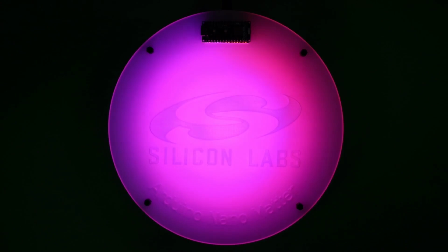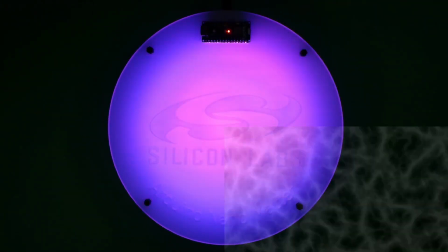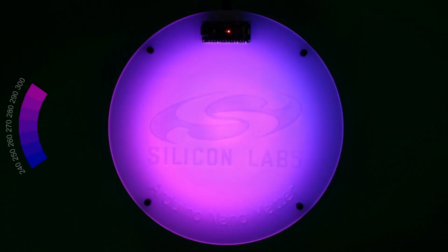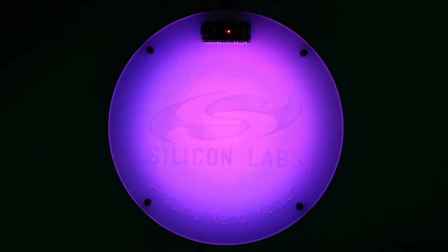The final stage adds 4 mood light modes that provide a plasma-like effect. If I press the button again, we can see the first of these. To generate this effect, a grayscale coherent noise image is used, and the LEDs take a slice of this image, mapping the 8-bit grayscale values to entries in the gradients we saw previously. In this first mode, we are using the gradient that takes the short path around the colour wheel, creating a subtle effect with the selected colours.